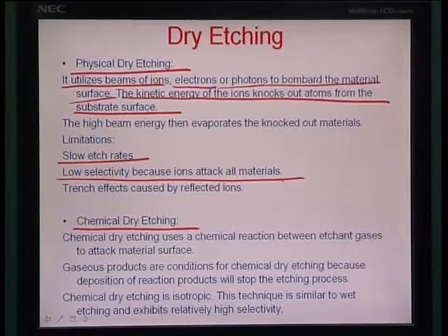process, because the ions attack essentially all the material surface which is available. It does not distinguish between material which is covered versus material which is exposed. It is an ionic beam falling on the material, so wherever it hits, it immediately starts attacking the material non-selectively. So, there is nothing called an etch stop until you reduce the beam power to 0. The etch stop is only controlled by beam power.